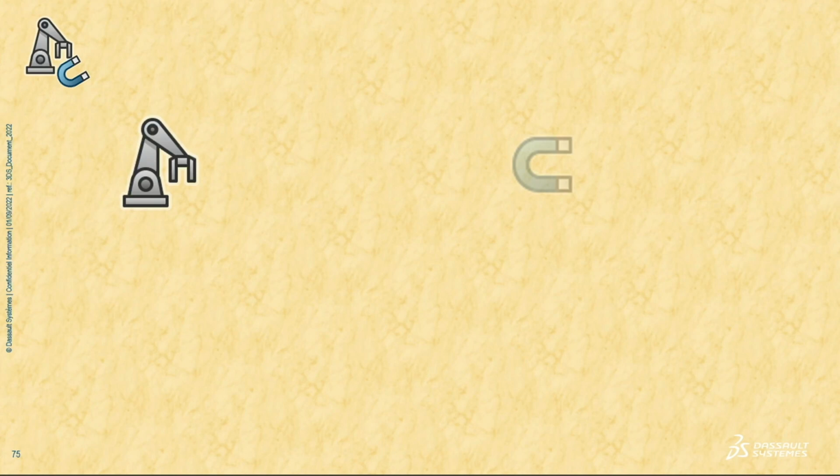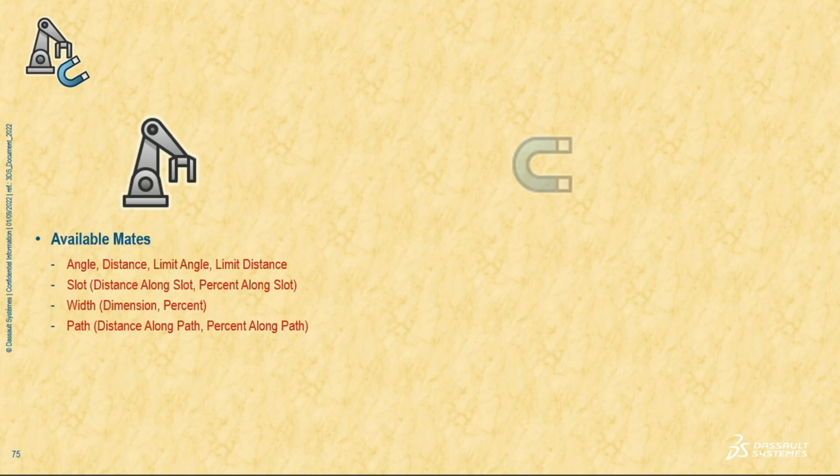All right, I mentioned there are several mate types available for the mate controller. It's the angle, the distance, limit angle, and limit distance. And the specific types of the slot, the width, and the path. So if it's floating, we can't, right? If it's centered, we can't. But there's the other options, like if a value is defined, right? That we can control with the mate controller.